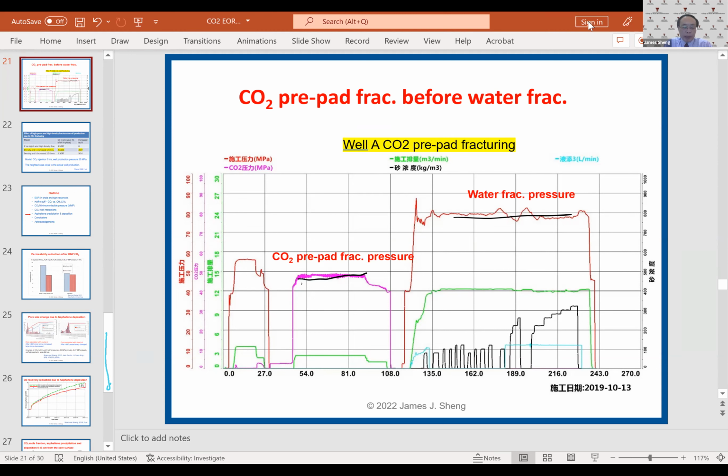It's not going to be very good because you have shale and tight reservoirs. Probably the more serious problem is injectivity and energy, not sweep efficiency. Sweep efficiency is only an issue if you have a breakthrough because fractures connect to each other. Therefore, we never did such detailed work, but I believe it should not be an effective way. Okay, and I will translate that into Chinese for them.